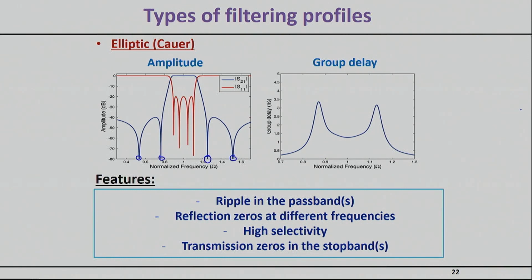These are essentially frequencies where S21 is identically equal to 0. This is what we'll specify as a transmission zero. By moving transmission zeros from infinity back to a finite set of frequencies, we achieve a far steeper curve close to the passband. And that's useful, particularly when you try to reject signals close to your passband.